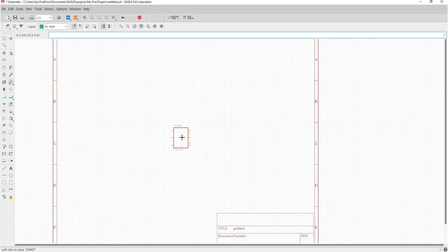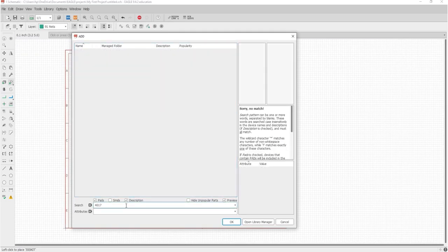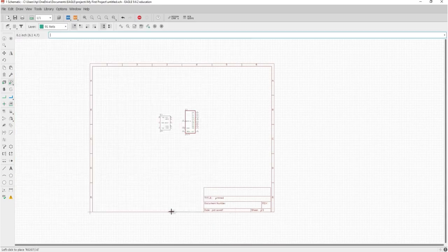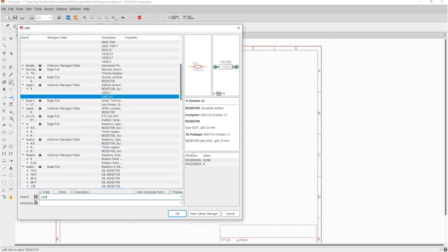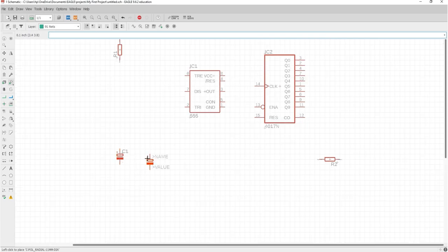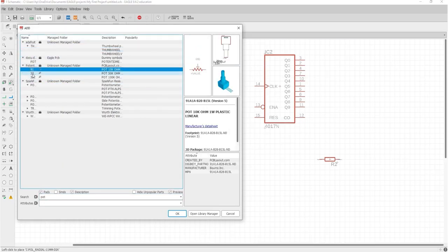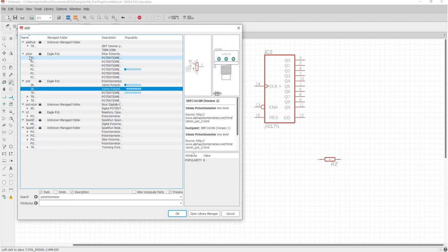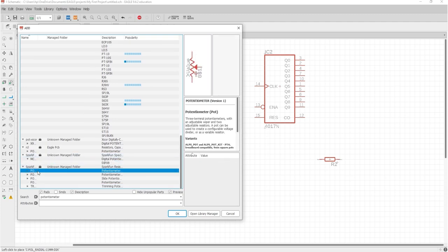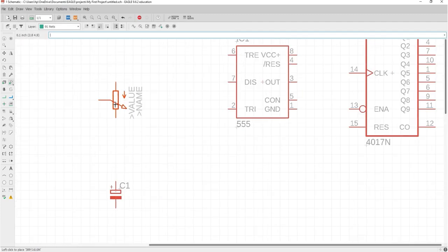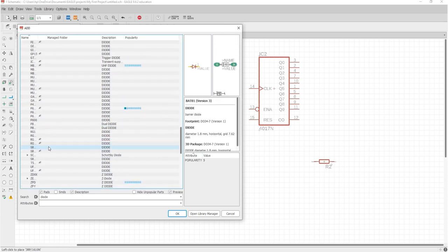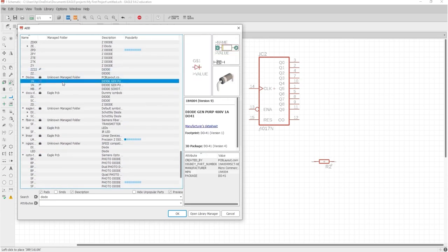In the Autodesk Eagle schematic editor, you can experience choosing the component symbol you want to use, which footprint of the symbol you want to use, and place the wiring diagram and connect each pin to another component's pin. This process is simple yet very crucial for your final PCB design.